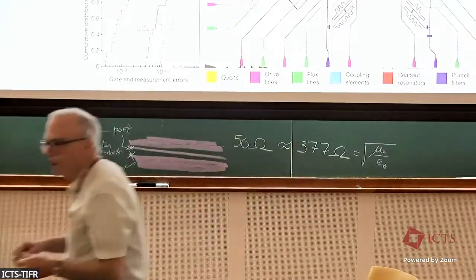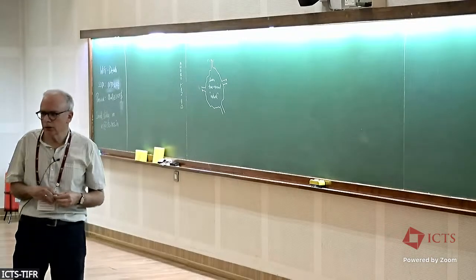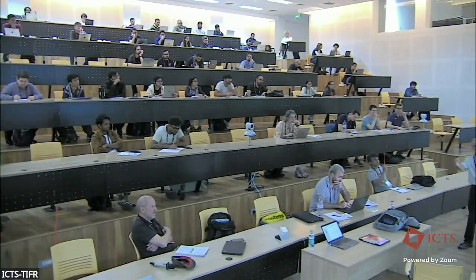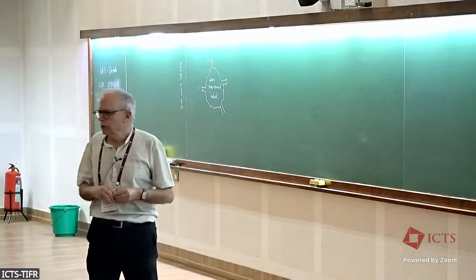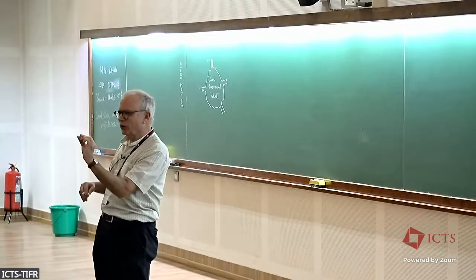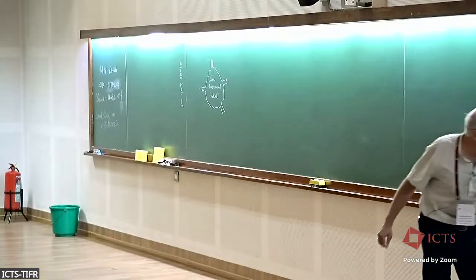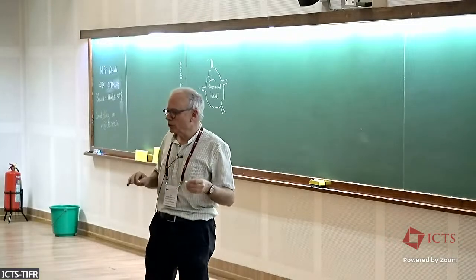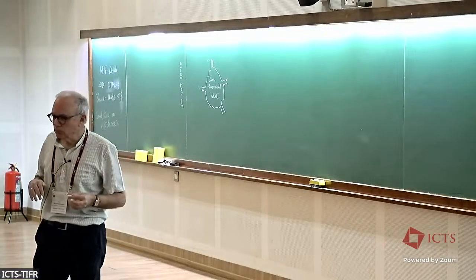Yes, the Josephson junctions are inside the qubits. And what's the scale of this? Good point. The scale is a couple of centimeters or something like that. This is a rather large chip, whereas the Josephson junctions are 100 nanometers. So this working area is extremely tiny. It's negligible on the scale, but it has an enormous effect on the dynamics, nevertheless. This is a metal and these are kind of etched on that.